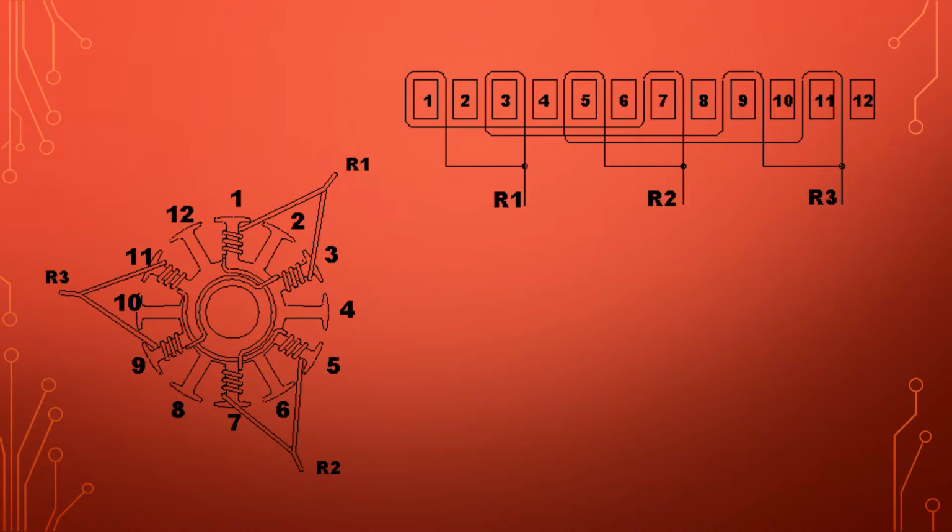The AC generator rotating field has 12 poles, with adjacent poles being of opposite polarity. Each pair of poles produces 1 cycle per revolution. Therefore, each revolution produces 6 cycles. The output frequency of the generator varies in direct proportion to the engine drive speed. A generator operating at 6,000 RPM is operating at 100 revolutions per second, or at 600 Hz.